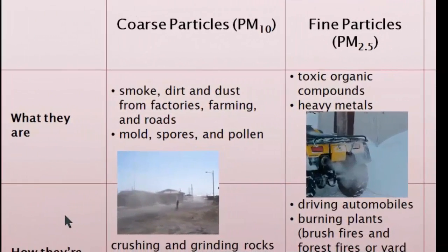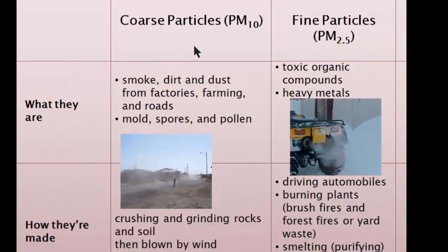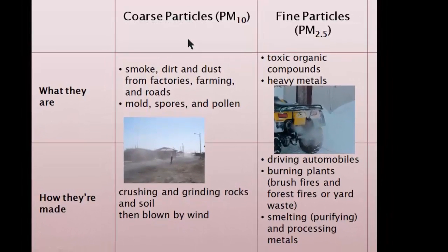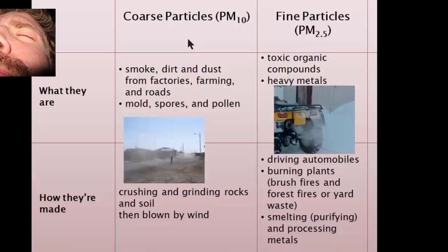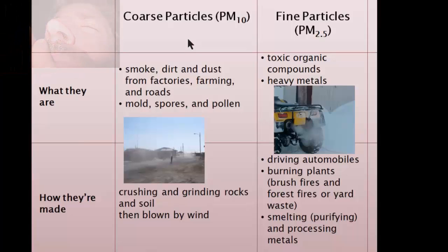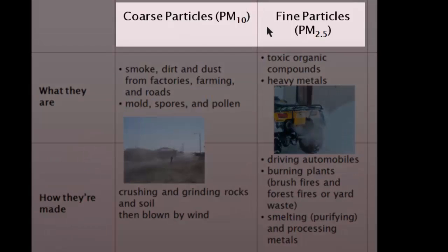First of all, what is particulate matter? We're talking about two categories in general, and of course particulate matter exists in a whole range. You've got really big chunks in the air, but we're not worried about the larger particulate matter. It will get filtered out by the nose hairs in our nose, but what doesn't get filtered out gets into our lungs, and that's what causes people having to go to the doctor because they've got asthma, they've got breathing problems. So the two categories are called PM10, or particulate matter that is 10 microns and smaller. And so that includes this other category of PM2.5, which is particulate matter that's 4 times smaller than PM10. So PM10 includes PM2.5. PM2.5 is really small.